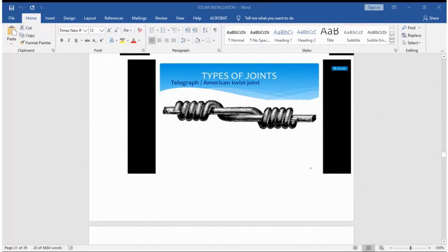So you said you first strip off the cable. So you can see you twist them. Then after you've made this type of joint, you can see this cable is the one that has these coils here, and this other cable is the one that is coiling around there. So they coil at both ends. So after you've made this cable joint, you solder the joint.